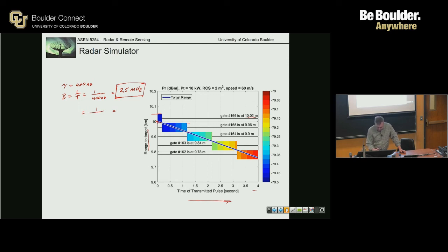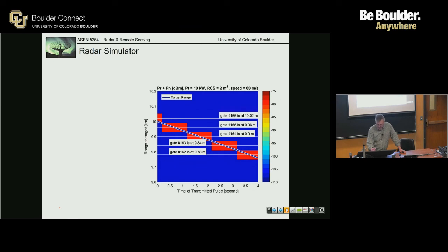And then you can plot this as the power received plus the noise power at each point. Since the noise figure was given, you can calculate the background noise, which was minus 106?